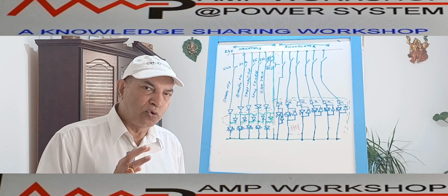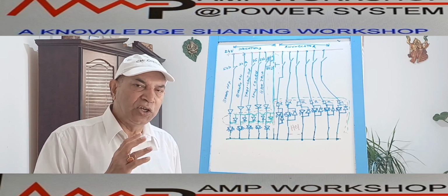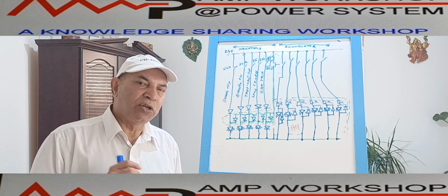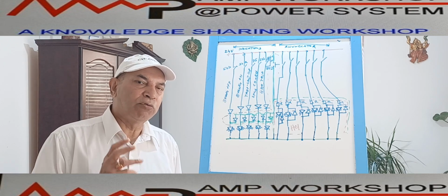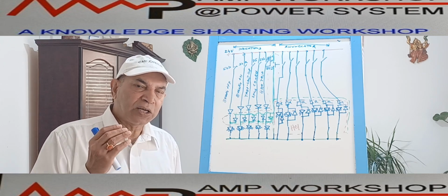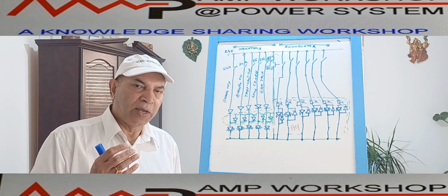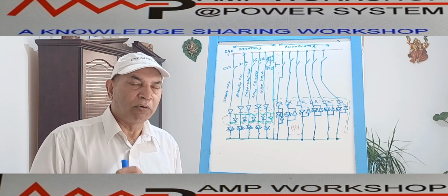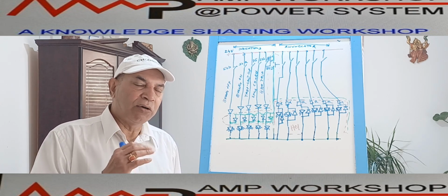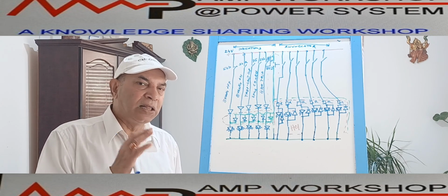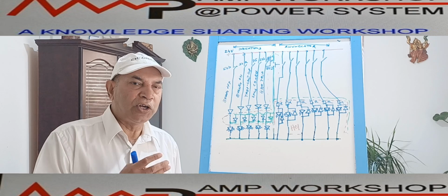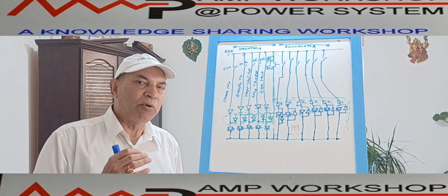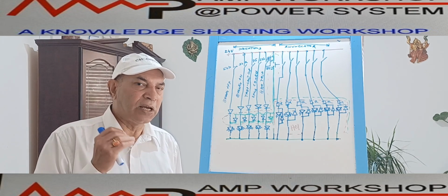In addition to these three statuses of the circuit breaker, we already discussed two parameters in the closing and tripping circuit. One is the trip circuit, which we monitor continuously as it is vital. So trip circuit monitoring also is done under healthy condition to confirm the trip circuit is healthy. Another is the spring charging motor, because that is a dangerous operation.